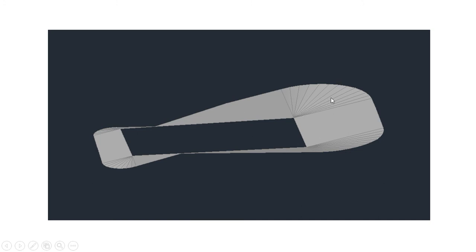4 in 1 is a preferred slope in terms of soil stability. Again, it depends upon other criteria too. However, it was structure fill on our site, so we decided to go with a 4 in 1 slope in here. So this is the bottom of the footing, and then this is a bit of a cut, and this is a bit of fill, and this is a bit of a cut in here.